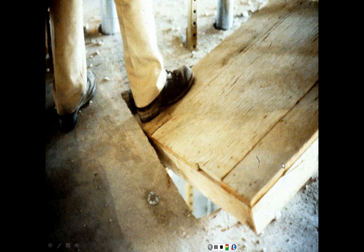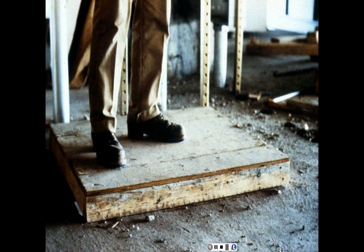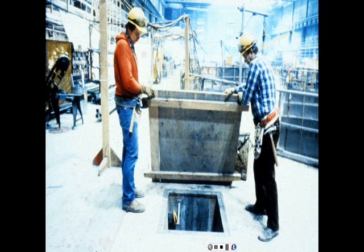Now that hole had a cover, and it seems like a good cover, but it was not positioned properly. So again, if someone steps on that, they're gonna fall through that hole. So here you have to show how you can position that cover so that it doesn't shift, doesn't move from its place. And now it's properly installed, and it's strong enough for a person to stand on top of it. This is proper protection. Again, it shows here the steps of the installation, and we can see that the cover is much wider than the hole to make sure that we cover the whole open area.